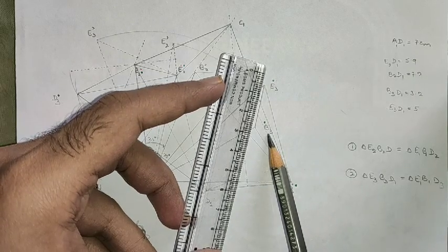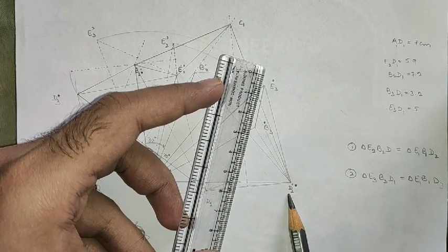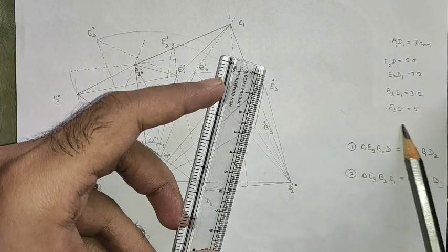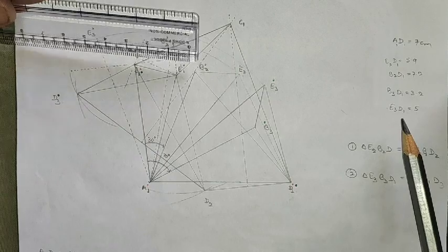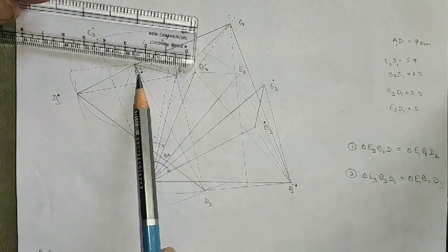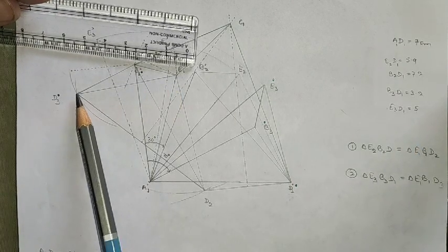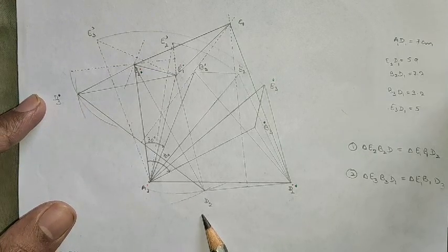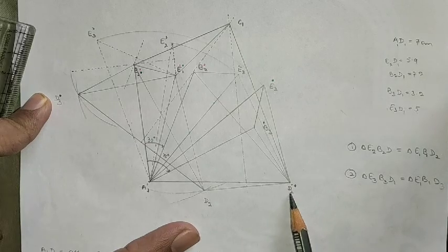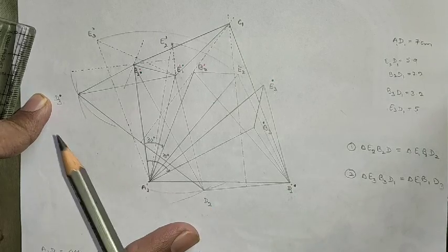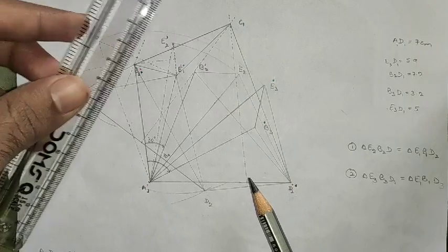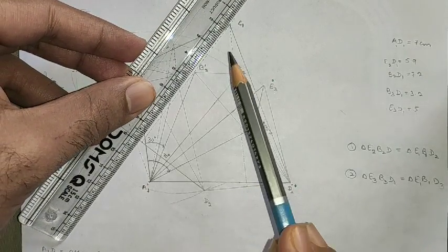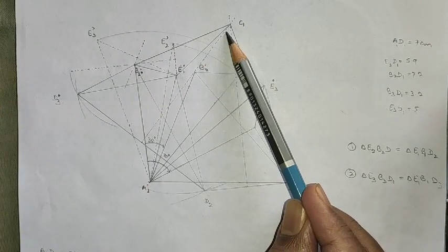From B3 to D1 we have first determined the distance, then again E3 and D1 we have determined it. These are my distances. And now measuring the same distances from B1 and E1, cutting an arc over here, we get the point D3. So we have determined the 2 points D2 and D3. Joining D1 to D2 and D2 to D3, and drawing the mid normals, this is my first mid normal, this is my second mid normal. These 2 lines intersect at a point C1 to get the other point on the coupler.